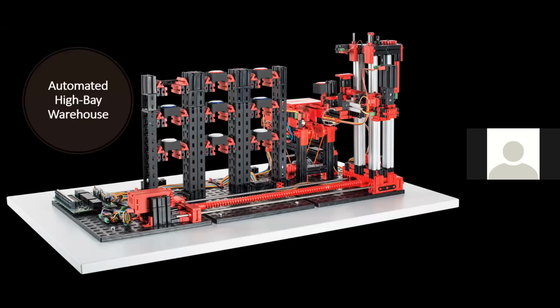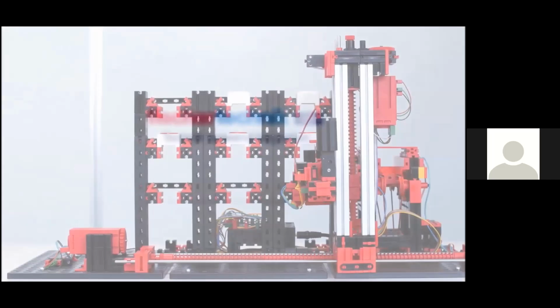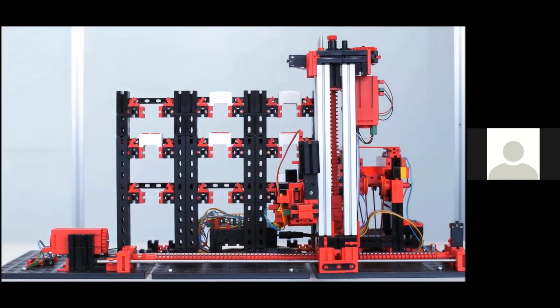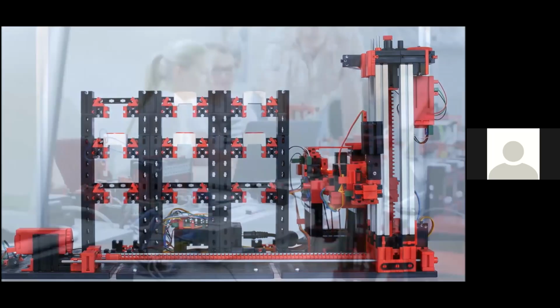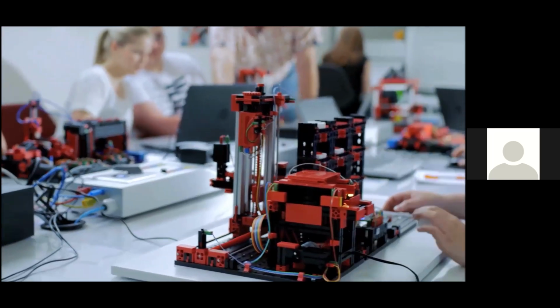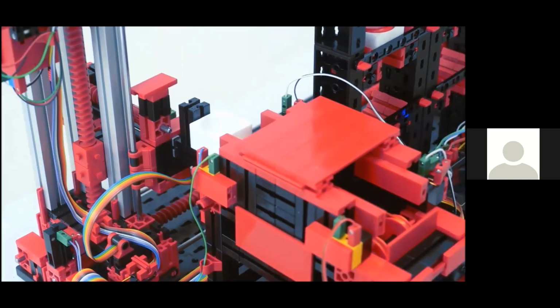Next up, we will look at the automated high bay warehouse. The model you're going to see here features a transfer station with conveyor belt, along with a shelf stacking mechanism for storing and retrieving workpiece carrier trays, as well as 9 individual storage spots. Components of this model include 2 encoder motors, 2 mini motors, 4 push-button limit switches, 2 photo transistors, 2 LED light barriers, and a selection of different colored workpieces along with carrier trays for each piece.